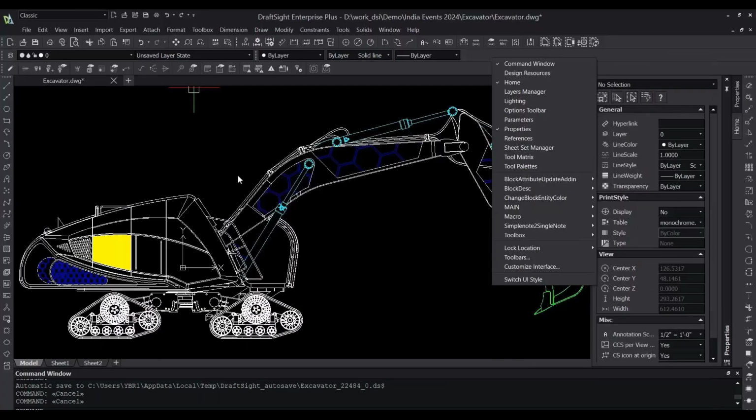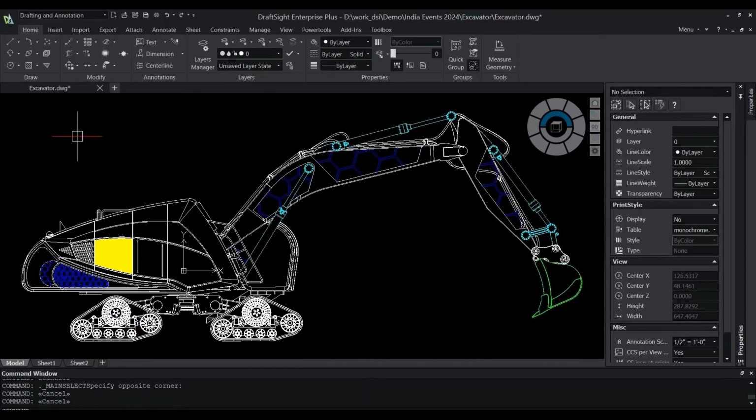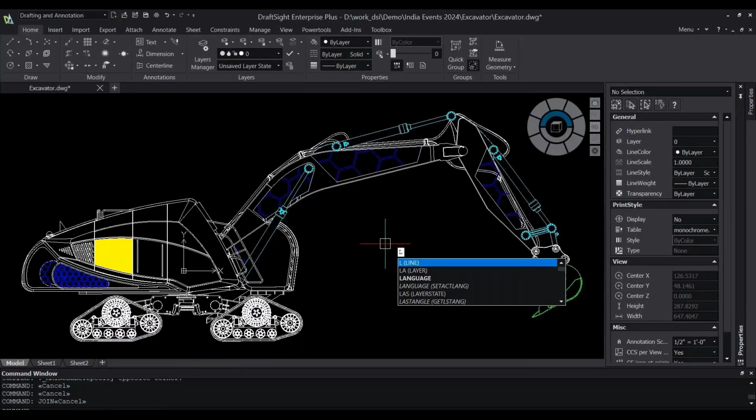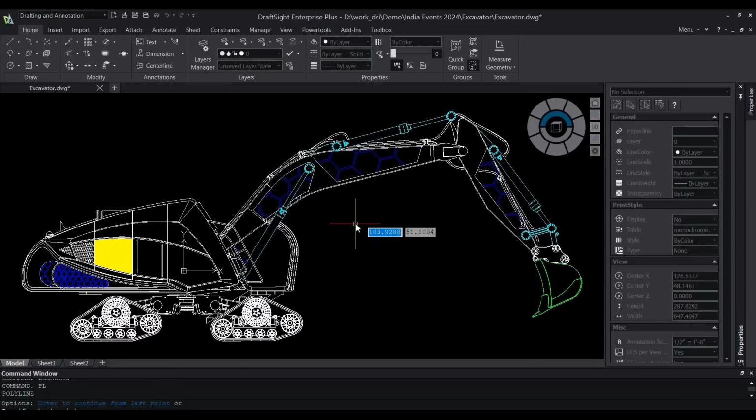Moving on from here, if you want to use your personalized workspaces, you can save them. We will be seeing how to do it later. Then if you look at the bottom, the command window is there, wherein you can simply type your command as you have been doing previously. Here is the join command, which in your normal 2D CAD is called weld. Then you can use the graphical interface to directly enter a command as well.